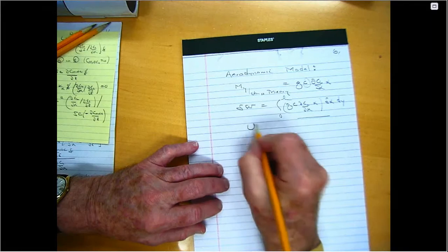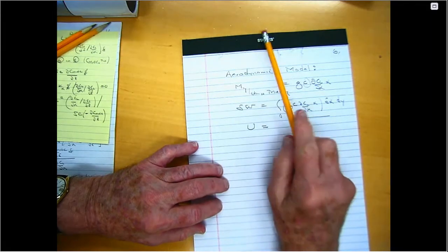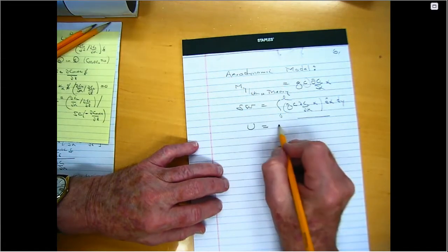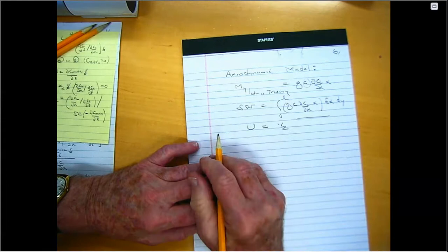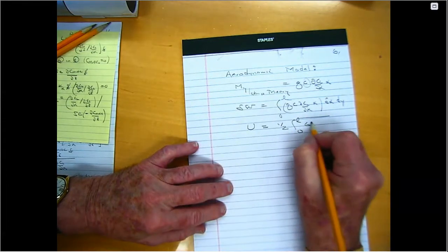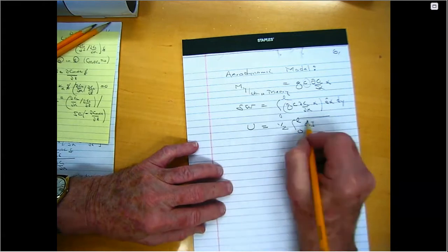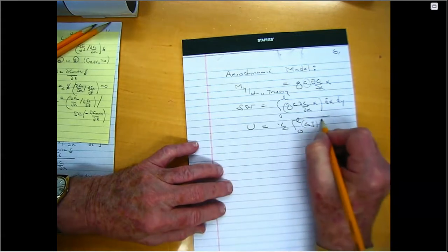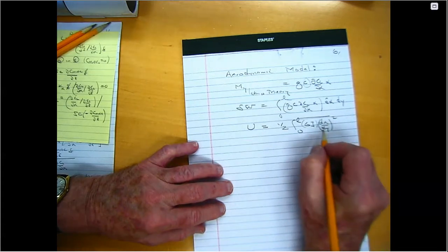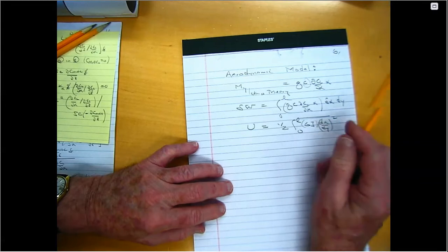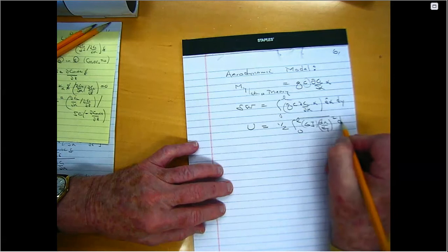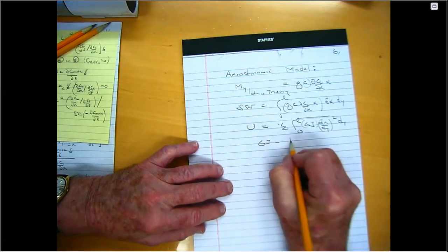Now, I was told by a reliable structural engineer that U is equal to 1/2, and you'll not be surprised that's 1/2, right? Times the integral from 0 to L of GJ, I'll tell you about GJ in a moment, times d alpha dy squared. You shouldn't be surprised by the square, because potential energies according to linear models are always quadratic in deformation, dy. And GJ is the torsional stiffness.